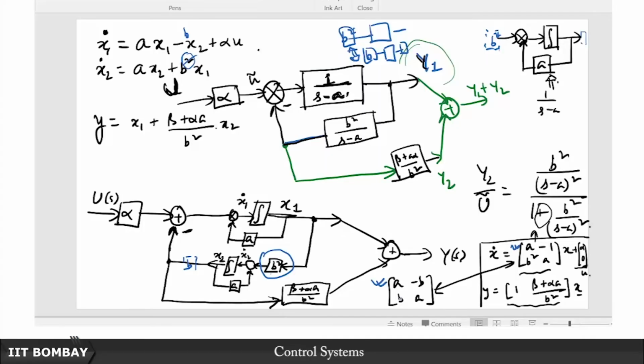Now with complex poles also, we see that you cannot realize them in this pure diagonal form. So the best you can do is get this 2 by 2 block to sit in the diagonal. This 2 by 2 block basically is a proxy for that diagonal 1 by 1, where you have s minus p1 and s minus p2 sitting on the two diagonals.